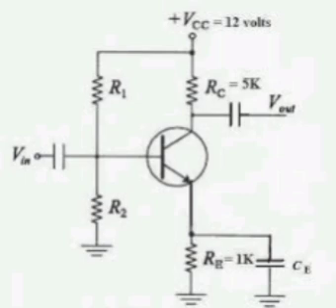In the Widlar current source, beta equal to 100 is large, hence IB can be neglected. 30 equal to IR into R1 plus VBE1, that is the loop equation. Then R1 equal to (30 minus 0.7) by 1 milliamp, that equals 29.3 kilo ohms.